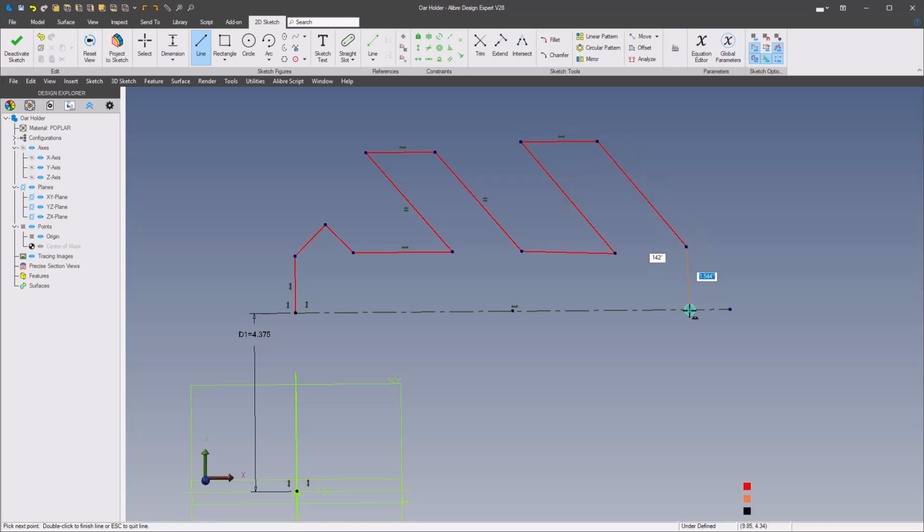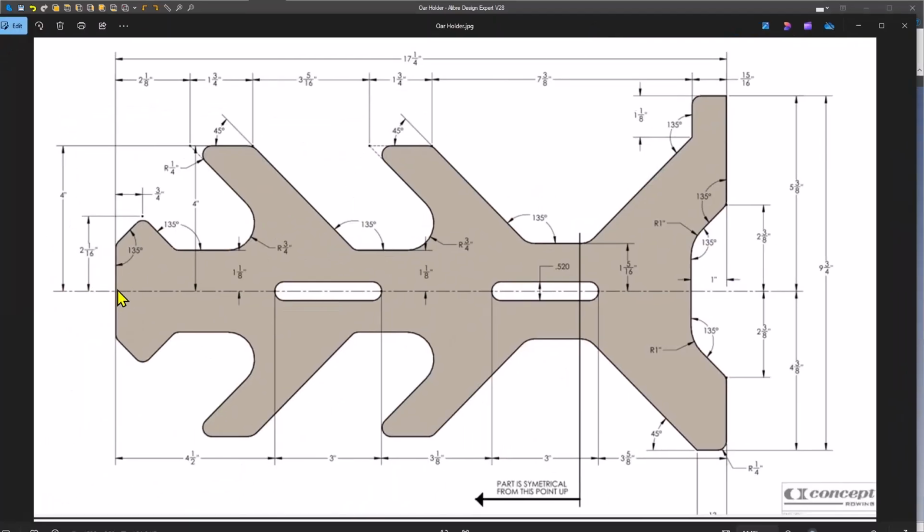And then I'll finish off here and end that. So what I've done so far is I've traced basically around here. These fillets come in later on, but I've got an apex between these two lines. Down here, come up to a point, sketch around this point, and I'm going to end right here at the intersection of these two lines, because everything to the left is symmetry and to the right will be non-symmetrical.